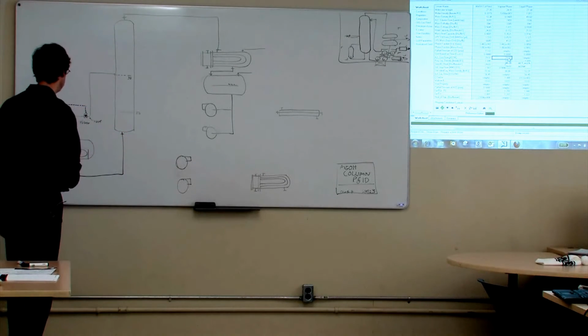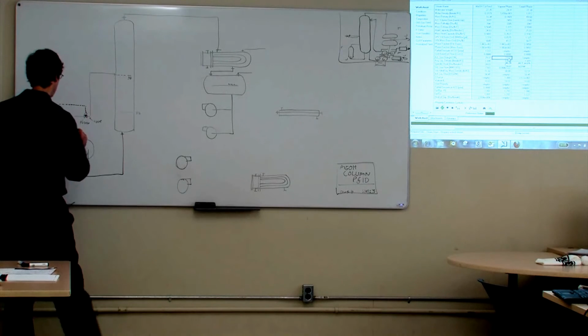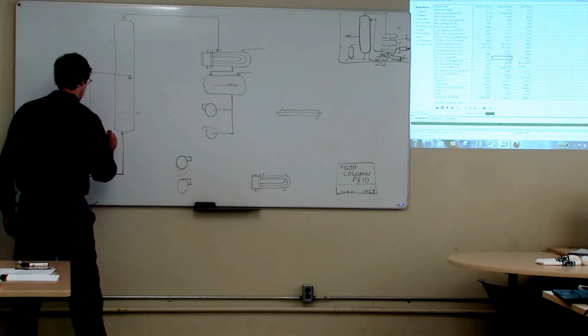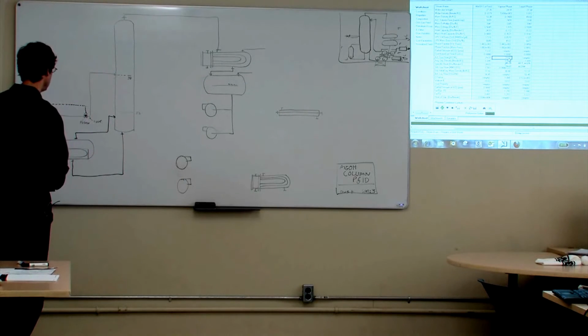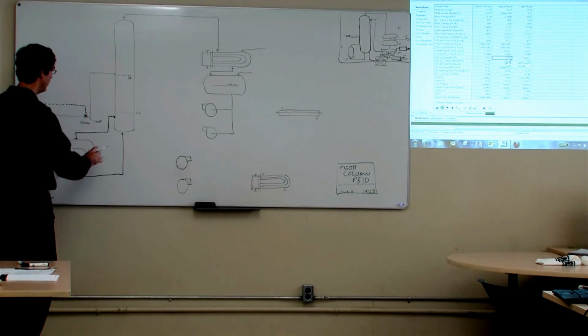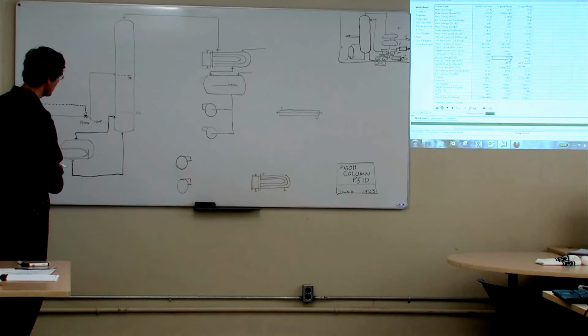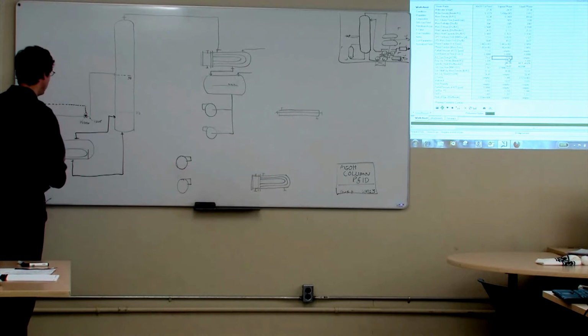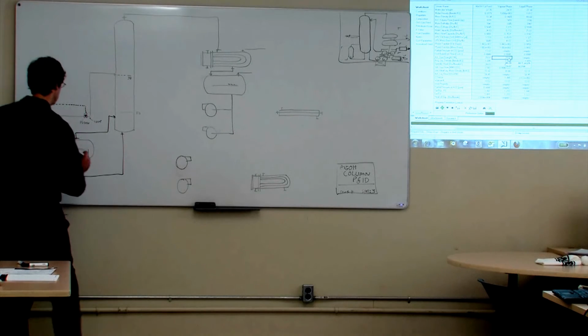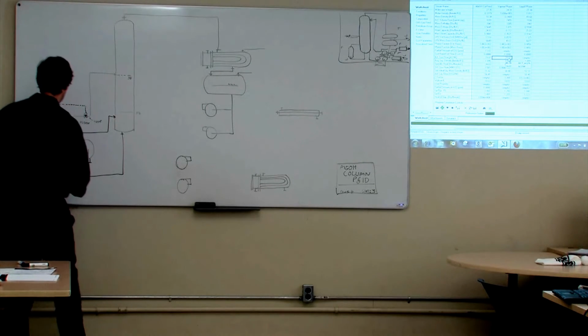Like that. Liquid into the reboiler, vapor back up into the reboiler there. I think I won't put any valves in there, so that if I have to do maintenance or anything like that on the tower, then essentially I'm going to have to shut the tower down and de-inventory it all before we can get into it. That may or may not be a good idea. Might want to rethink that one over the next couple of days.